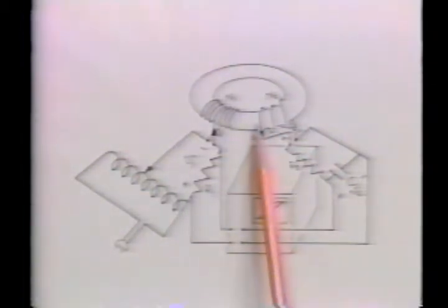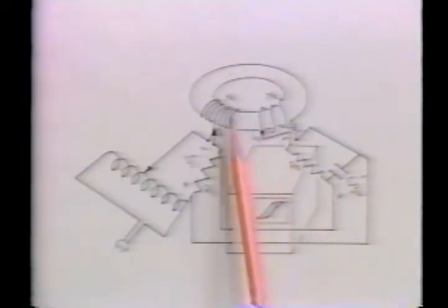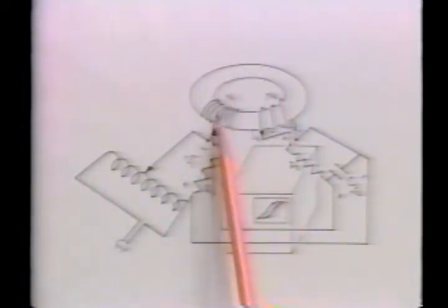An RC integrating network on this sensing or secondary coil integrates the terminal voltage so that the flux linking the coil is recorded. The circuit acts as an integrator because the capacitor has a reactance at the frequency of operation, 60 Hertz, that is much smaller than the series resistance.